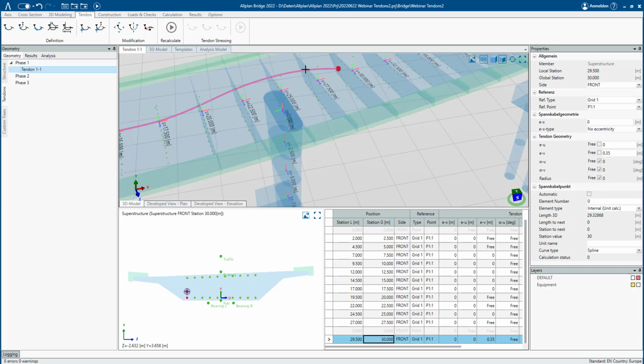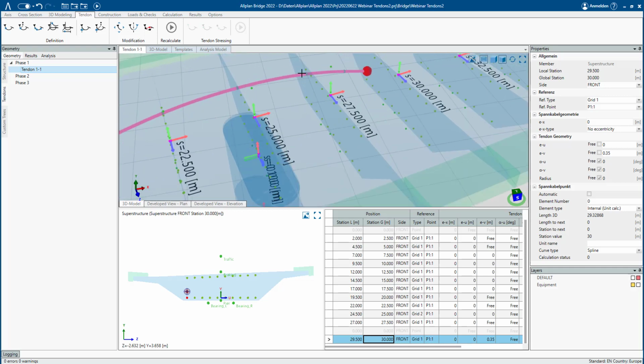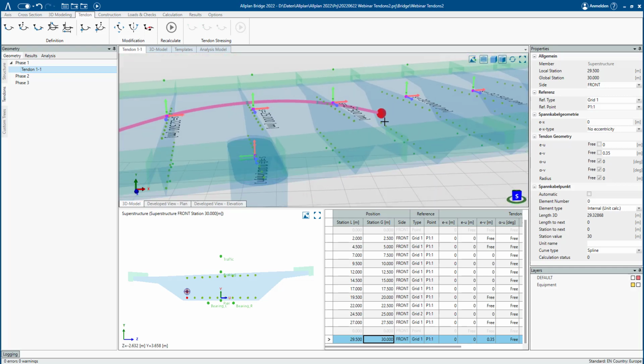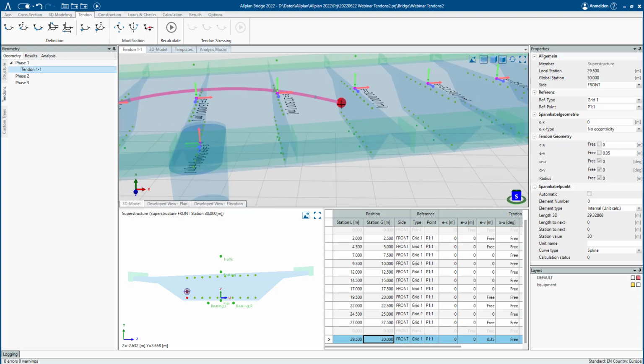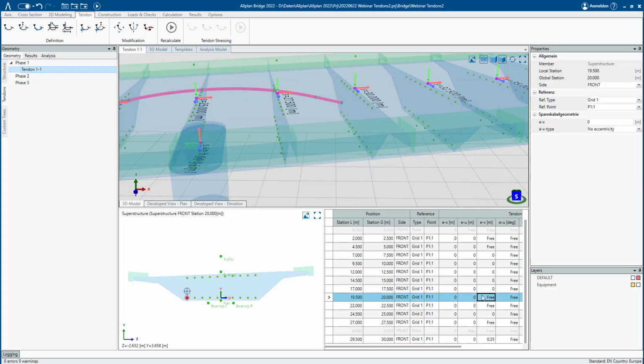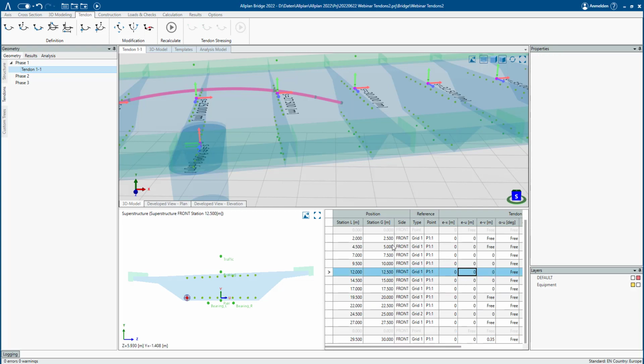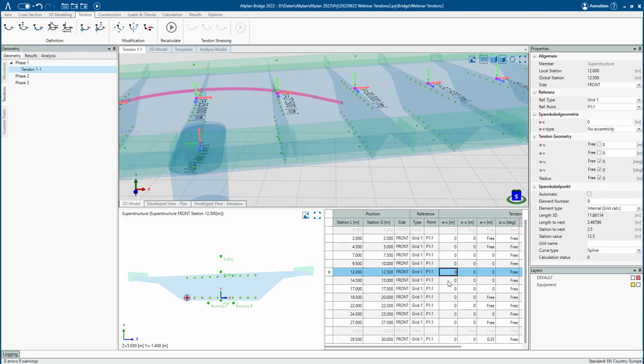Yeah, also if you want to adjust certain elements, like here, move something not completely on this stage, move it a bit further to the side, and it's also possible in the vertical direction, this is the V here in this case, in U direction, in the horizontal direction, also in longitudinal direction with EX to move it further on or backwards without creating another cross section or station actually. Yeah, okay.